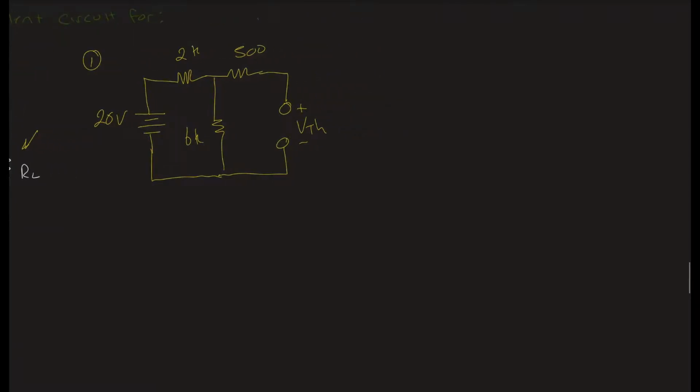So again, we just need to break this down, and I wanted to point this one out specifically because again, notice, how does the current have to flow? Well, the current flows this way, it comes up to here, and all of it must go down. Again, remember, if it's an open circuit, we can't have any current going that way. So actually, when we're solving for Thevenin, this breaks down the exact same way.